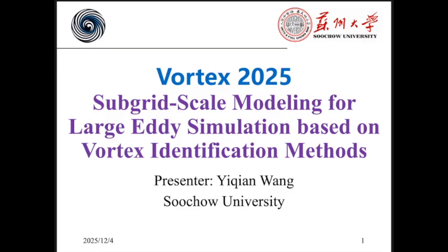It is my great honor to present our work here, and the title is Subgrid Scale Modeling for Large Eddy Simulation based on Vortex Identification Methods. The core idea of this research is to introduce advanced vortex identification methods into the construction of subgrid scale stress models for LES. Our objective is to more accurately capture and simulate the critical vortex structures and their energy transfer processes in turbulent flows.